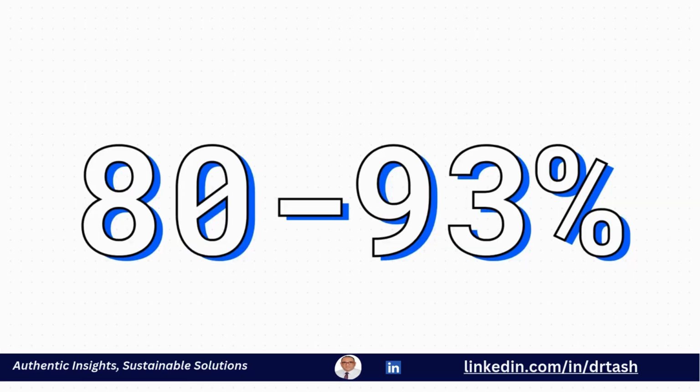And just consider this for a second. It's a staggering figure. Up to 93% of the electrical energy you're paying for to run a compressor just turns into heat. But here's the twist. That heat isn't just waste. It's a resource. You can recover up to 90% of it and use it for other processes, like heating water or buildings.